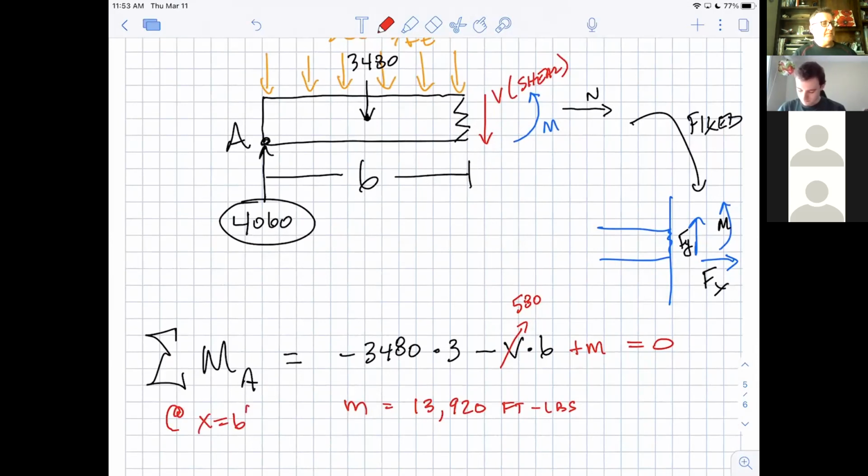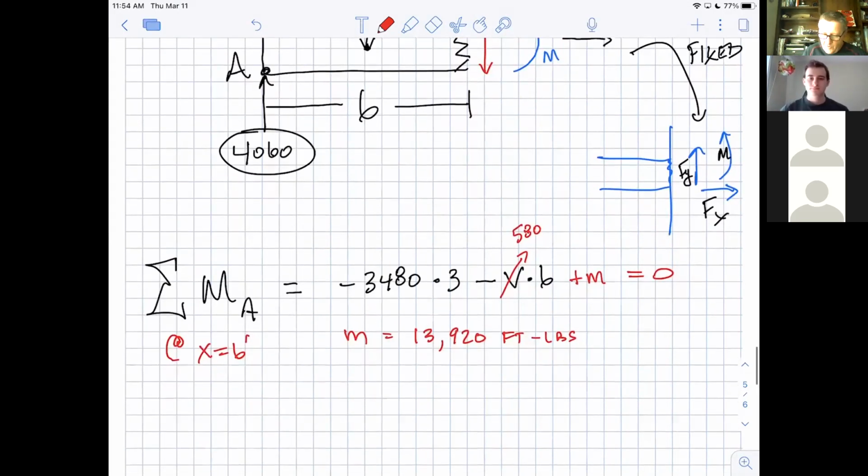Whoa, 6 feet in. That's a big ask. Do you agree with that? Now, remember my idea a minute ago? Hey, cool, let's build a beam that has no middle. Does it make sense? The moment says, better not do that. There's no shear there, but that middle's got to be able to resist 13,000, 14,000 pounds of desire to rotate. So we better not have nothing in the middle. That works great for shear, but it doesn't work very well for moment. Whew, that was a bad idea.